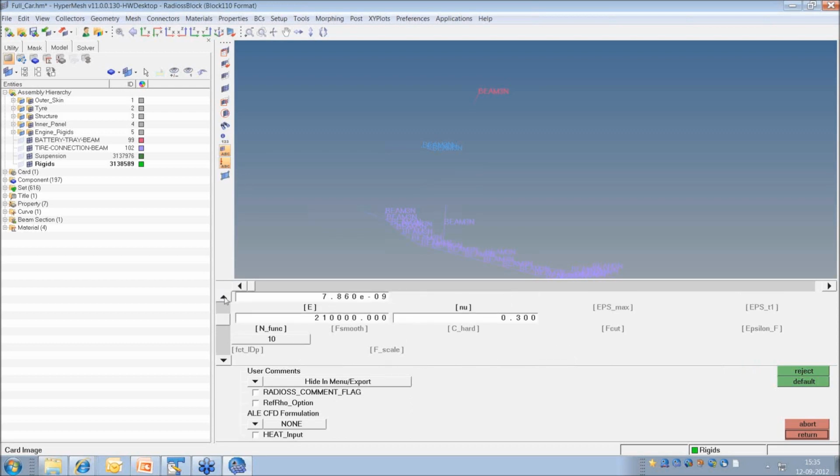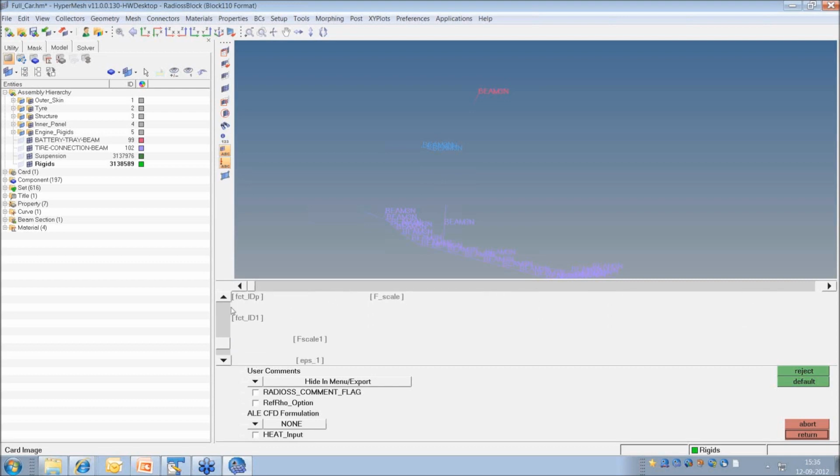Normally in the solver, when we explain this material, we'll explain how we get this strain rate dependent data and how we can use it. Here I'm just creating only one stress strain curve. I specified the number of curves which I'll be inputting here as 1. At a later stage, I have to call that function here.